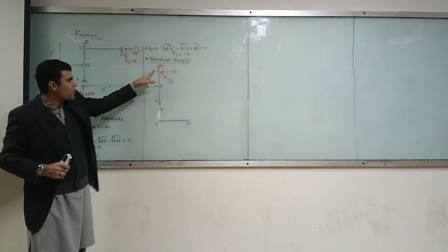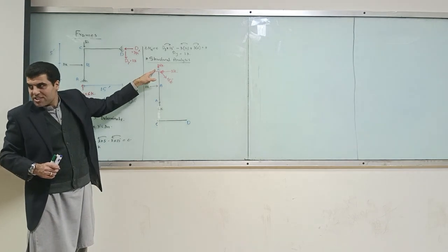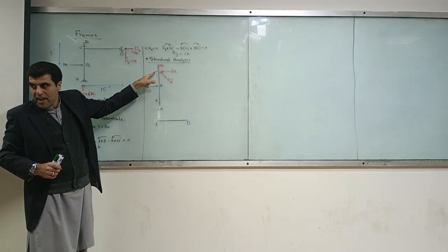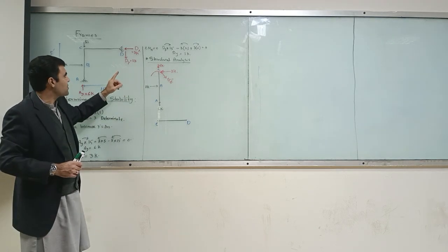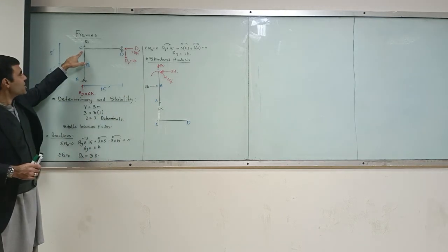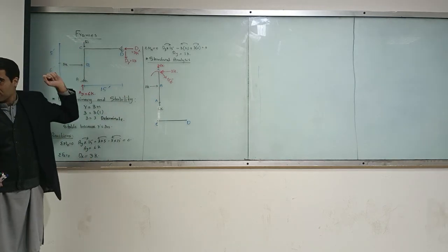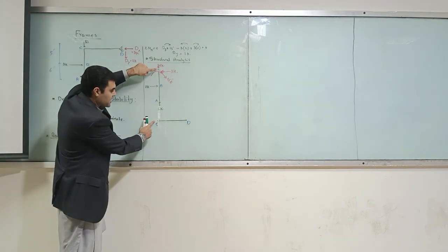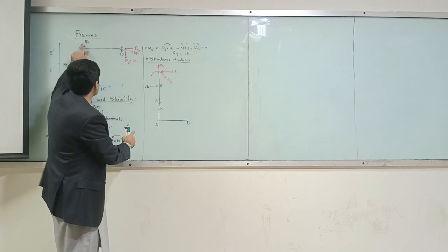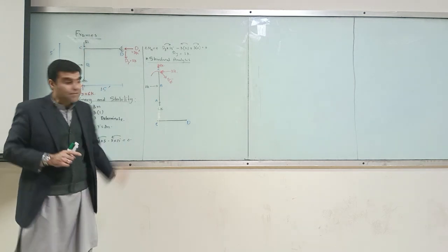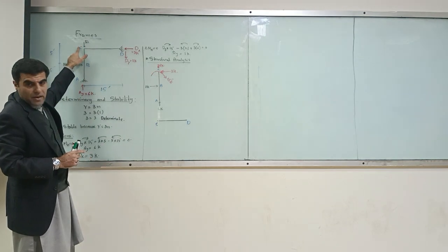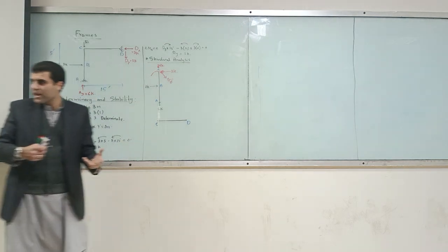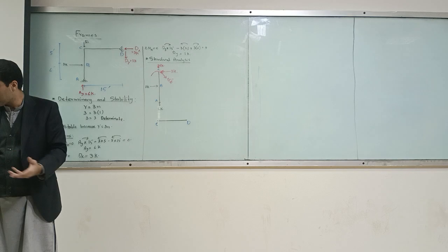So according to this equation, we have made this joint, we have 6 kip applied over here. But externally there is 5 kip applied on this joint. So the summation of this joint and this joint must give us 5 kip. If this 5 kip was not applied, I would have put a 6 kip in the opposite direction to make it in equilibrium.